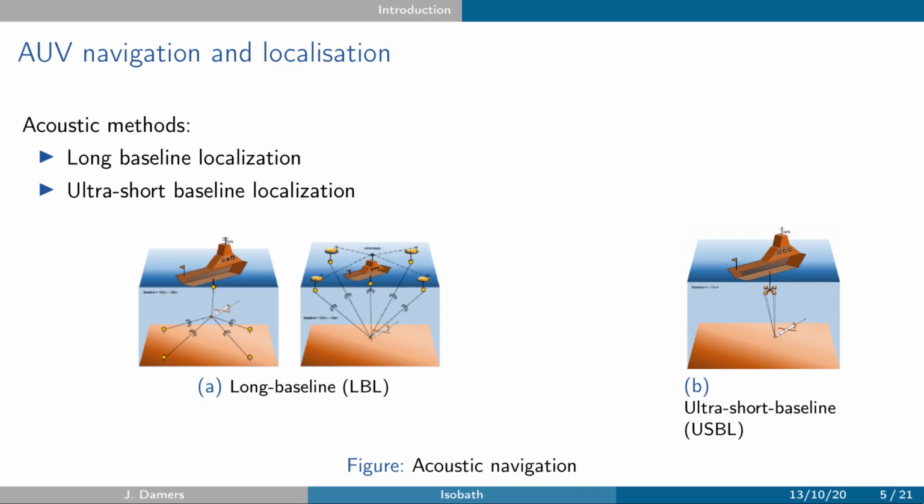And then there are the ultra-short baseline localization methods. Here the AUV itself doesn't know its position, but thanks to a hydrophone attached to the surface vehicle, the surface vehicle will be able to listen to the AUV to know its absolute position.